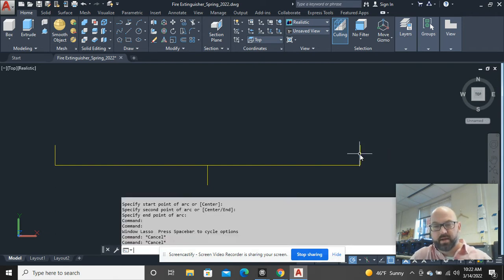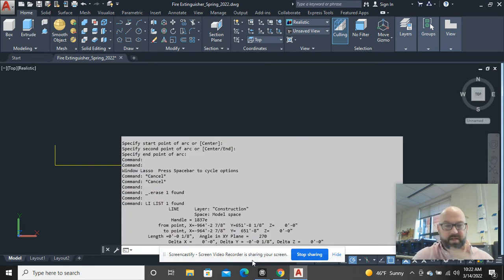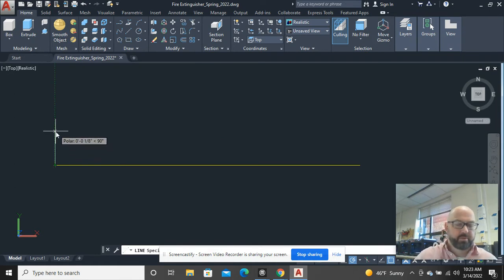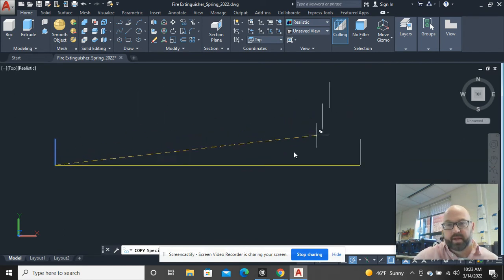So in order to correct that, I'm just going to add the tiniest amount. That was 1/8 of an inch, which is 0.125. I'm just going to add to that 0.125. We're talking now the fifth place, thousandths of an inch. So I'm going to say 0.130 will be my distance. And that's only changed it by 5 thousandths of an inch, so you're talking about like a human hair and a half at that point.